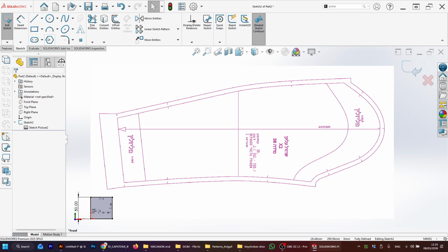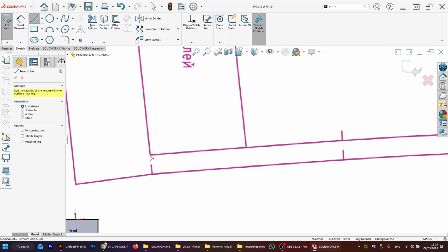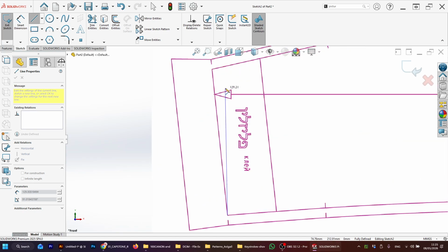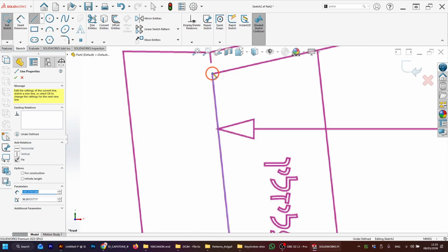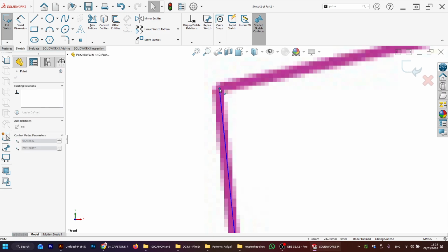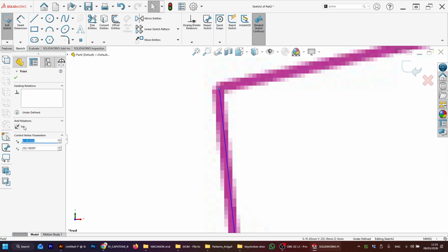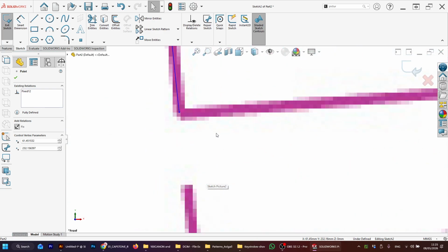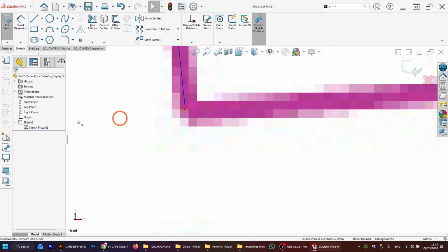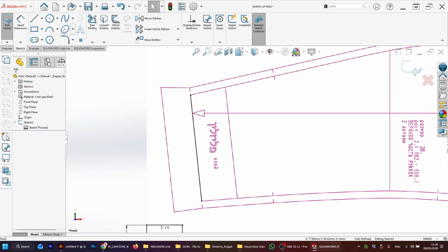So let's start sketching. I start with a line, get close, look, place it in the corner, go up, if I can get close and even be really perfect. If I'm happy with that point, I can take it, click on it, fix. I just added a rule, this point will not move until I release it. Click, fix. So this is why I won't have surprises.